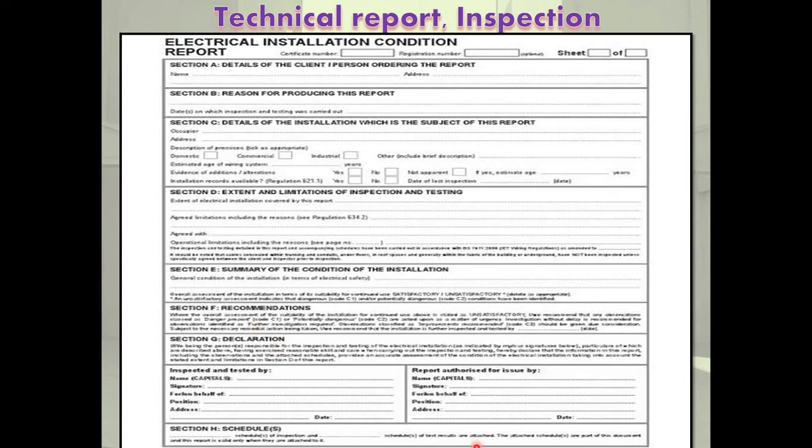In addition to this, it includes results of various mechanical tests like leveling, alignment, measurement of air gap, vibration, etc. It also includes electrical tests like insulation resistance, polarization index, earth resistance, reading for every hour. If drying of the winding has to be done, reports of filtering of the oil, different results of the tests made on transformer, motor, generator, etc.